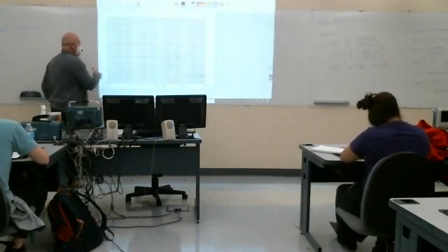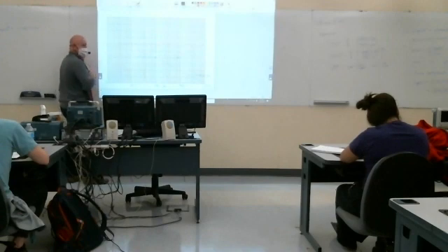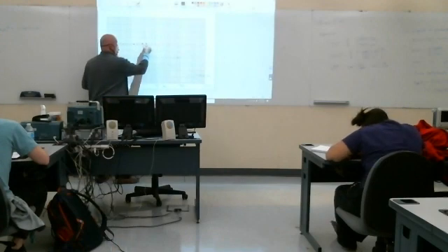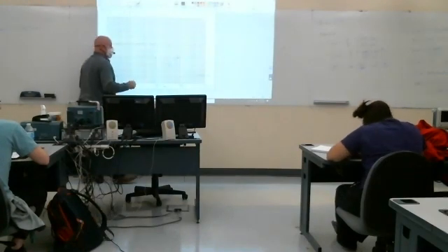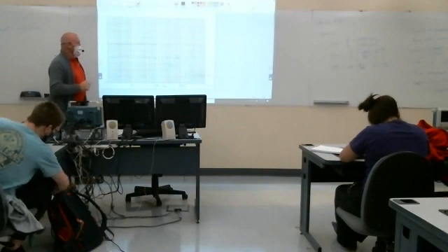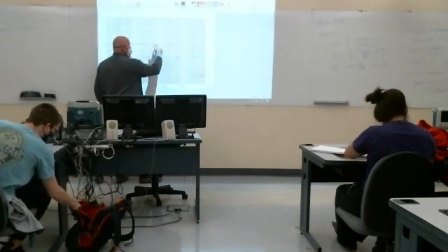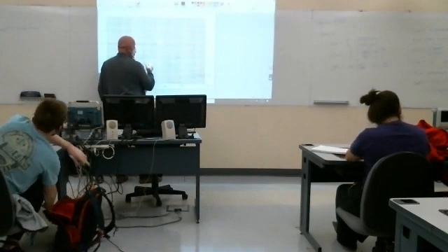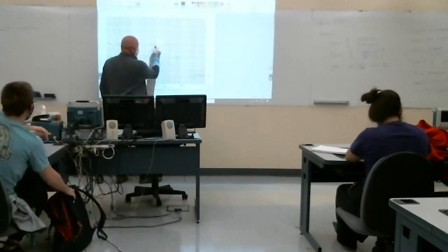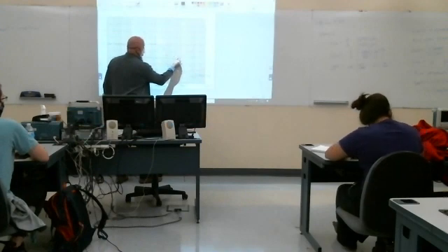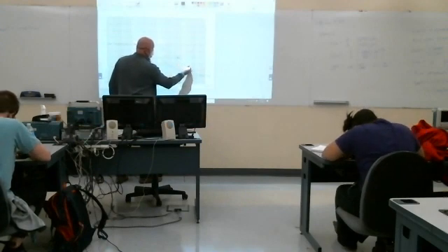Now, you start over here at the left. I just have the constant term. The other two are zero. So to graphically add them, I'm going to follow my constant term out to where I get to my first critical frequency. Since I'm just adding, now I'm going to start going down at 20 dB per decade. So I'm actually just going to draw a parallel line, parallel to this negative 20 dB per decade. So this really would take me to this point, okay? And that would continue on forever, right?